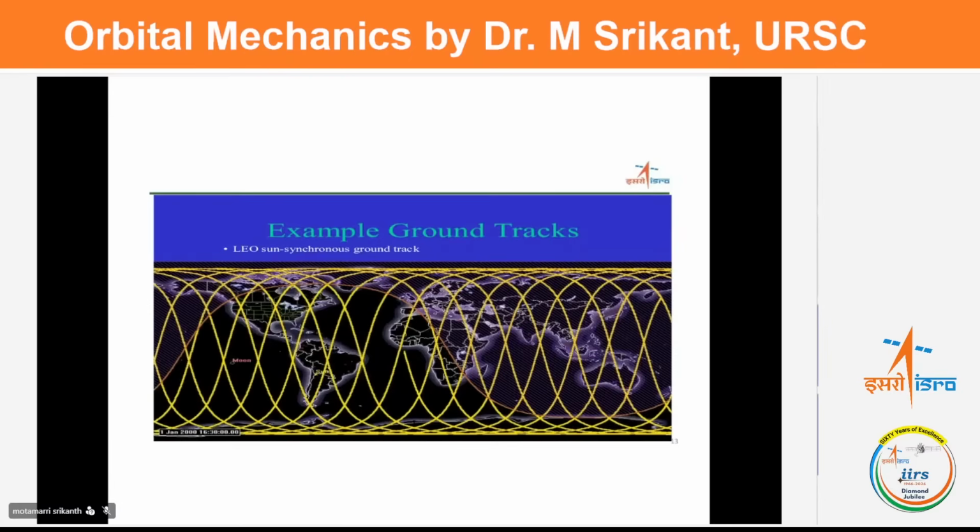My question was whether it is easier to operate polar orbiting satellites or this kind. Sir, I don't see any difficulty. The only thing is with respect to momentum management. When we use magnetic torquers, the field strength is minimal when you come close to the equator. So torquer capacity and disturbance are slightly different. That is the only major difference.